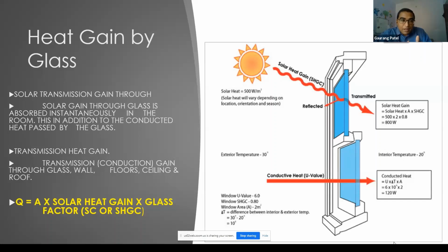Okay. So first there will be convection, then conduction, and then again convection, if I take heat from outside to inside. Here also, like I had given an example of conductive heat transfer, that is the overall heat transfer value, because that is a combined one, convection plus conduction. It won't be purely conduction or purely convection.